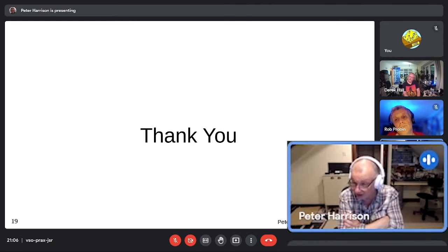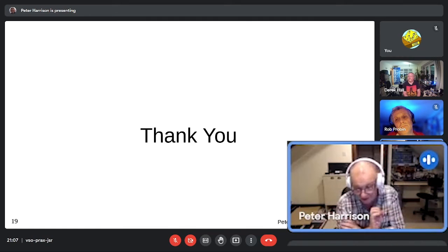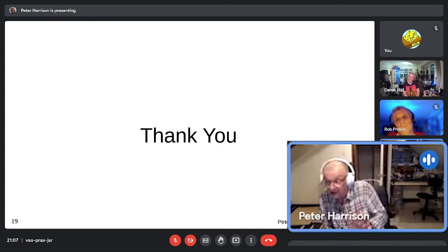Okay, but you have two things acting together to put it right. And so if you were able to look at the graph output for the robot with the wrong constants in, you'd find that the controller output is now much more busy. It's trying to do much more, something like the first example that I showed you, right? Because it's trying to compensate, and it actually may even be compensating the wrong way.